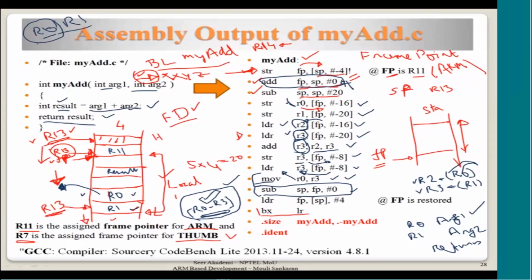So the SP is getting back the same value, because SP was decremented here. Prior to that, SP was loaded with the value with which it started off. After this -4, SP is now added to 0 and we get that SP. SP is now coming back. It was here, -20 was done. Now SP is coming back to this location. I am writing it here so that you understand it.